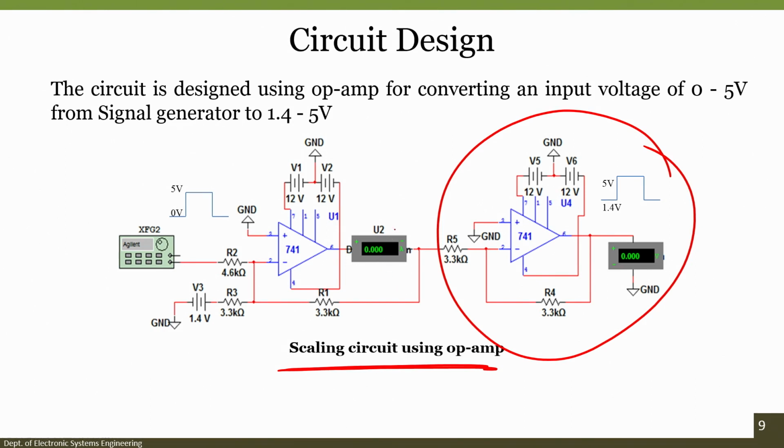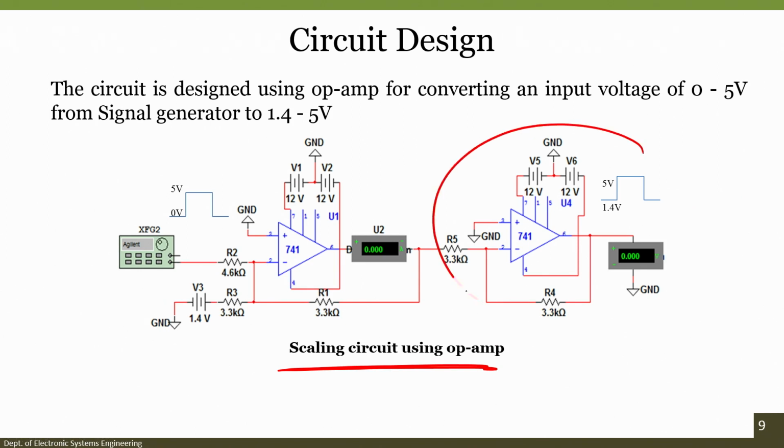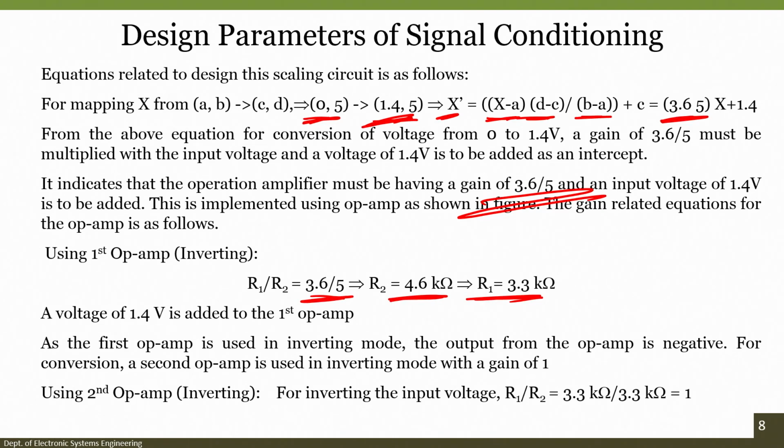At the output, the phase would be shifted because of the inverting op amp, and here again if you use an inverting op amp, the phase will be shifted back, which is similar to the phase of the input signal. That is the reason for using a two stage operational amplifier. Again, this can act as a buffer or unity gain amplifier because the gain is 1, right. For an inverting amplifier, our gain equals minus Rf by Ri, right. That is why we just consider R1 by R2.